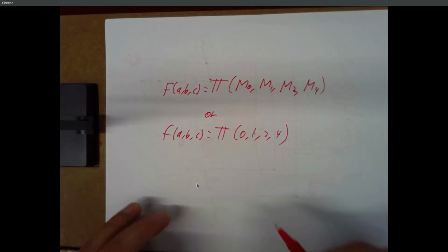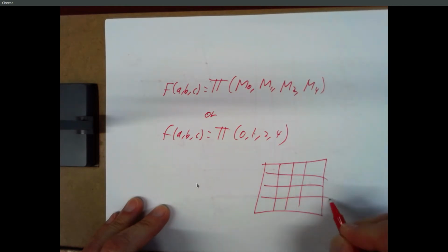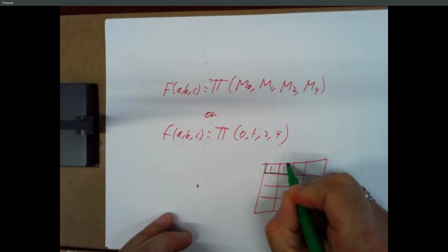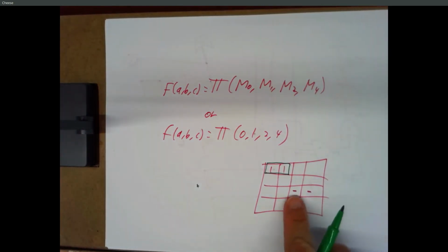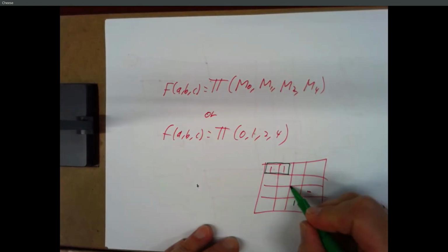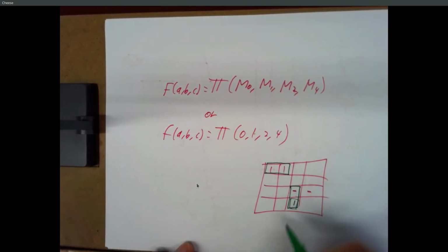Right. So if you have a Kmap like this, I would cover these two ones with a 1x2 rectangle and I'd be done. There's no reason that I would cover those dashes because that's just going to add more hardware. It's going to be another term in my expression. And if I cover these, I'm saying these should be 1, but I don't care if they're 1s. But if I had a 1 sitting out here, I would go ahead and cover these two. And that's going to be better than just covering this 1 by itself. Okay. So they're optional covers.